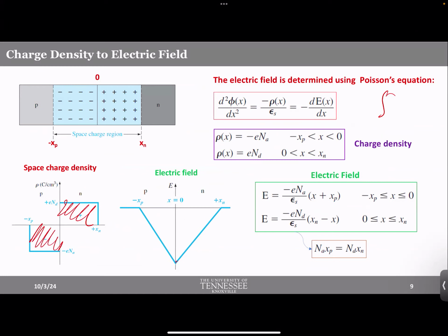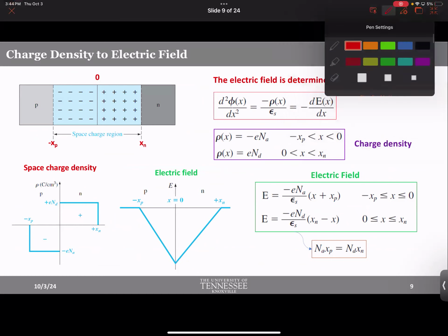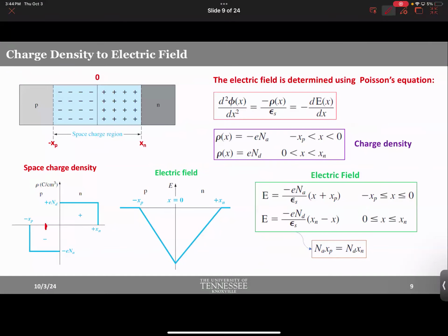Folks, remember, at this point, the electric field should be equal, don't you think? So the electric field is basically nothing but the area under this curve, the maximum electric field. So by equating area, you are calculating the electric field at this point. So notice, very simple, if I make this dimension narrower, what should happen to the height?